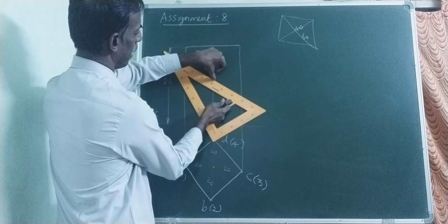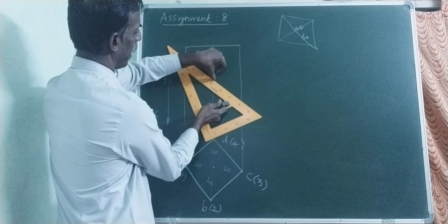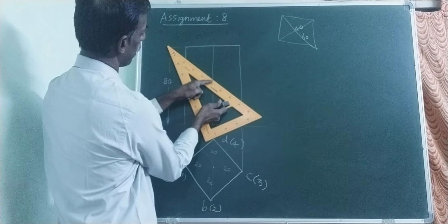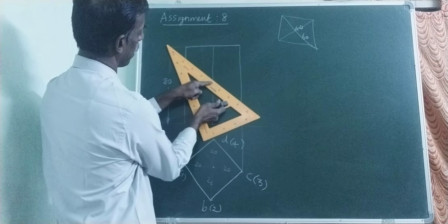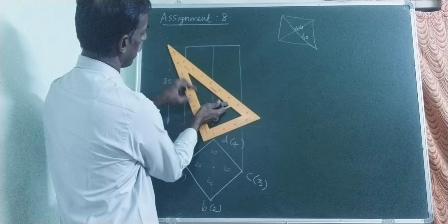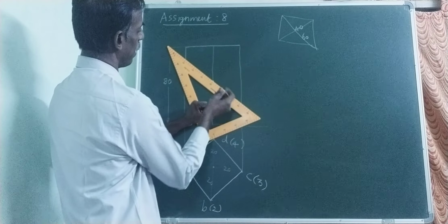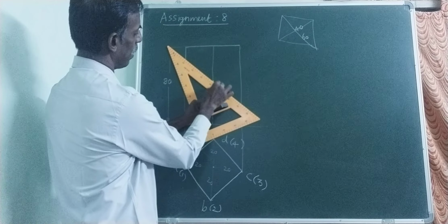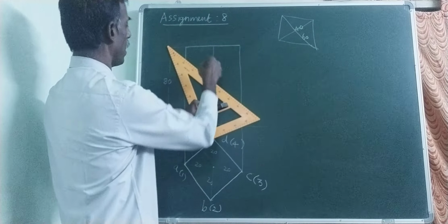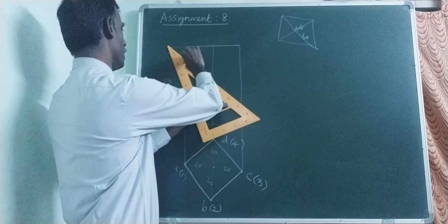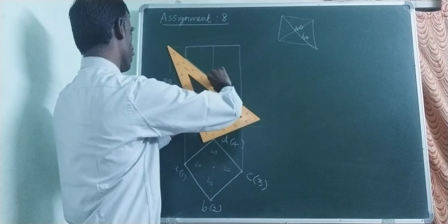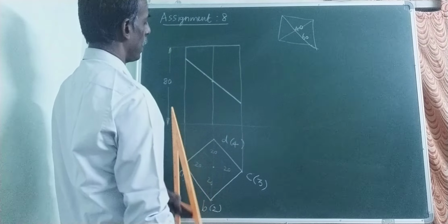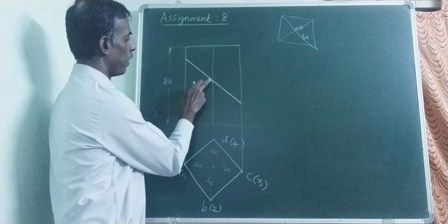When you rotate like this, at one particular point you will get 30 on this side and 30 on this side, on either side from the midpoint of the axis. So the total diagonal distance will be equal to 60 mm. So this is the cutting plane position and angle. The midpoint is the position.